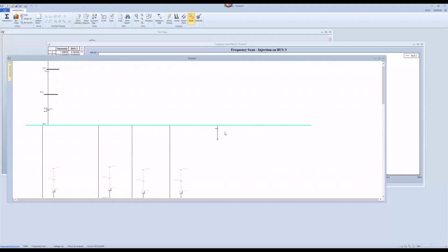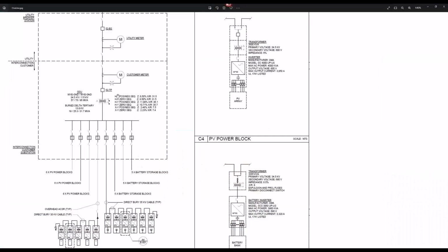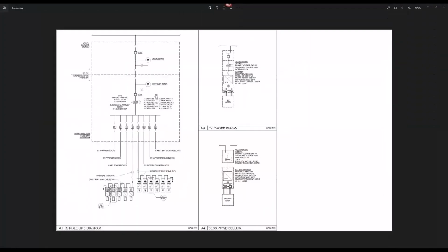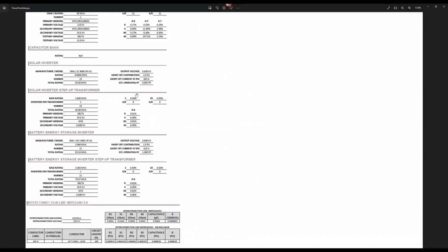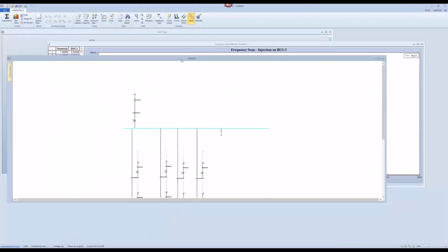If you do, please install them together with some harmonic filters at the IBR, right? So those are what we have prepared for today's webinar, including the data collection: you collect the one line, and then you collect the power flow data for the main power transformers, for the GSU, for the inverter sizing, and most importantly, ask the manufacturer for the harmonic current injection spectra, right? That's all. We can have all the data we need to build our power plant model like what we did just now.